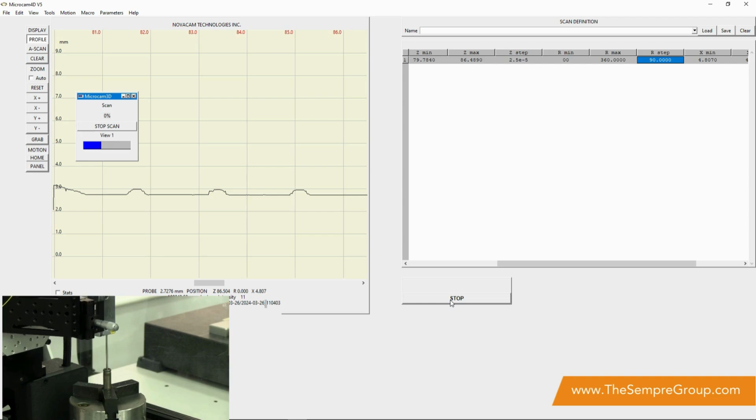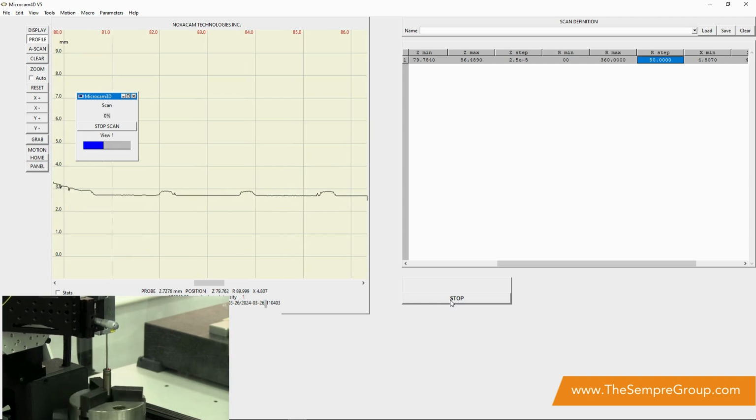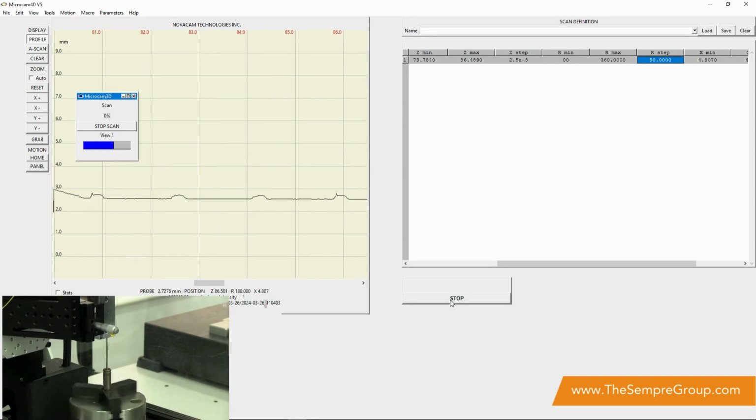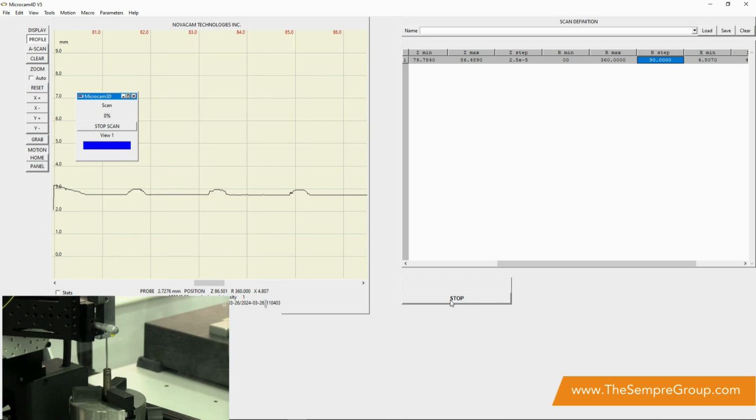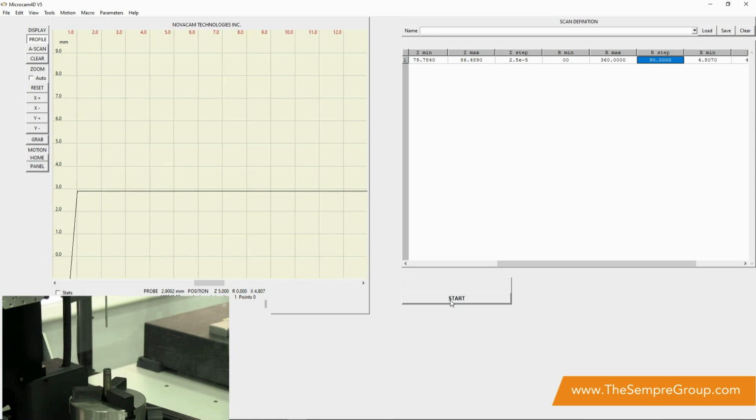So we can vary the speed depending on what it is you're trying to do. Obviously on a thread, the slope angle is relatively difficult to obtain optically. So the slower we go, the more detail we're going to get within those profiles to be able to look at things like the flank angles, pitch lengths, that kind of thing. So as we're scanning through here, obviously the component's rotating. So the scan is completed. So again, this is all optical on this internal feature.